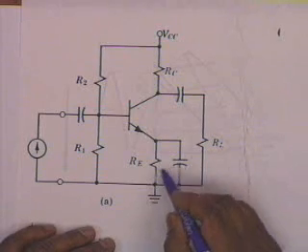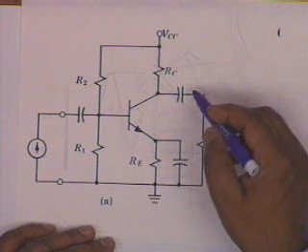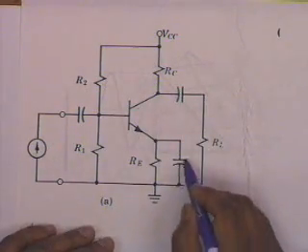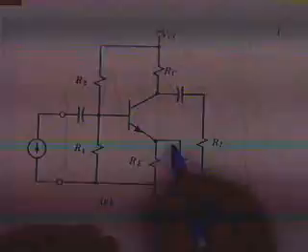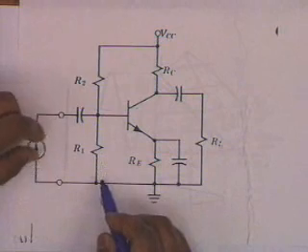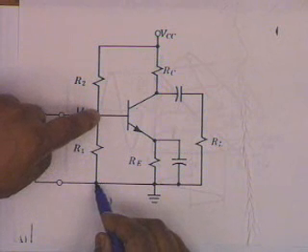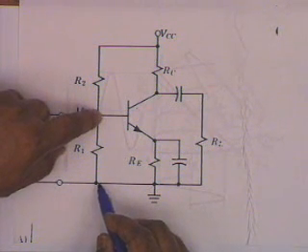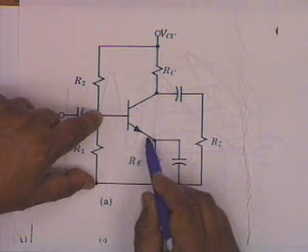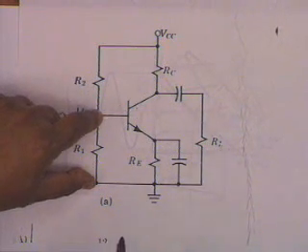Third capacitor, the capacitor across RE. Well, obviously this capacitor also is to be AC short, signal short, and DC open. All right. Now the third capacitor is inserted here for one reason. The reason is the following: the signal voltage should appear from the base to ground. Part of the signal voltage is from base to emitter, and part of it is across RE. Is that clear? We don't want this.